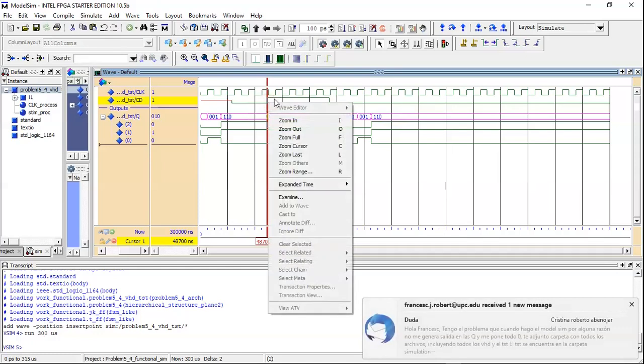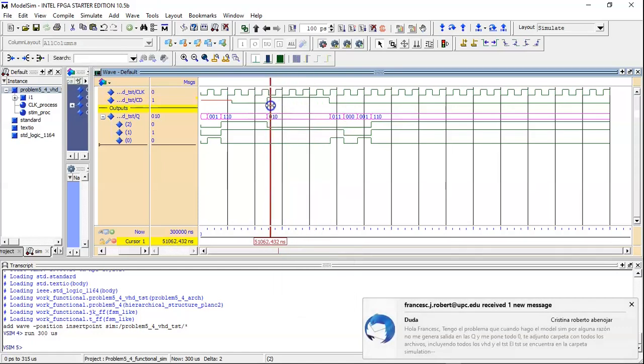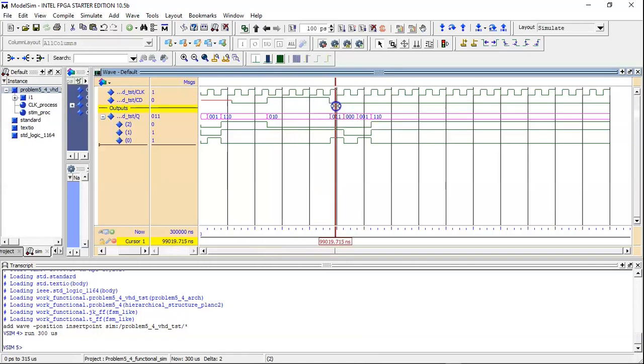Now is when the system is initialized, and the initial value, because of the connections, is 0, 1, 0, and then the system generates 0, 1, 1, 0, 0, 0, 0, 0, 1, and finally 1, 1, 0, and it does not change at all, never, right? So this is the expected result, and I guess that this is exactly what you got from Proteus.